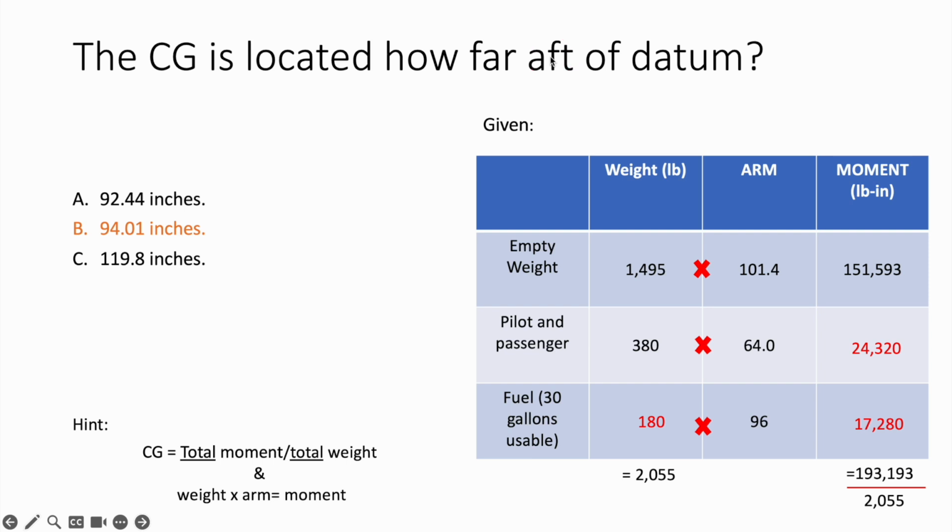And so remembering back to that diagram, anything to the right of a weight and balance diagram is considered rear or aft. So you're kind of imagining, instead of a diagram, imagine the plane is like this. And so we're trying to measure how far aft or backwards is the center of gravity. So in this case, it's 94 inches aft of the datum.